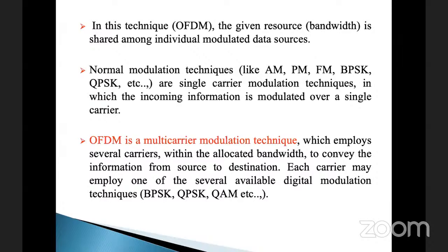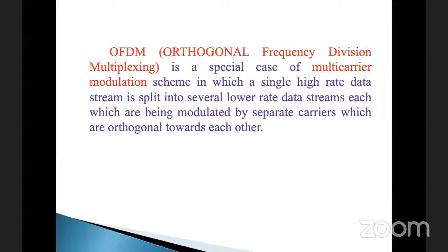So this is a multi-carrier modulation technique. It employs carriers, allocated bandwidth, and conveys the source to the destination using formats such as BPSK, QPSK, or QAM.